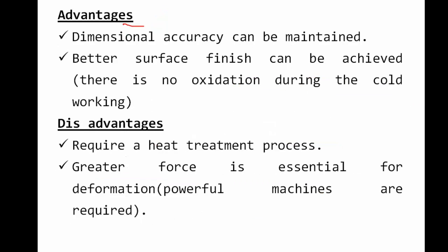What are the advantages? Dimensional accuracy can be maintained. Since the temperature is below the recrystallization temperature, we get better dimensional accuracy compared to hot working, and a good surface finish can also be achieved. There are no accidents during the work. Disadvantages: it requires a heat treatment process.